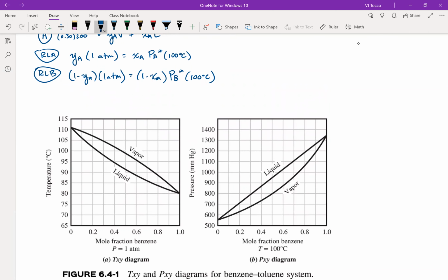So you should get the same thing on the TXY diagram. My temperature is 100. So I just have to draw points there and there. This is where my tie line is. And I draw little dashed lines straight down so I can read the plot. And this is the disadvantage of doing it graphically, is you oftentimes lose the precision that you would have with your calculator. I'm going to call that 0.26 and 0.46. Doing it the TXY way.